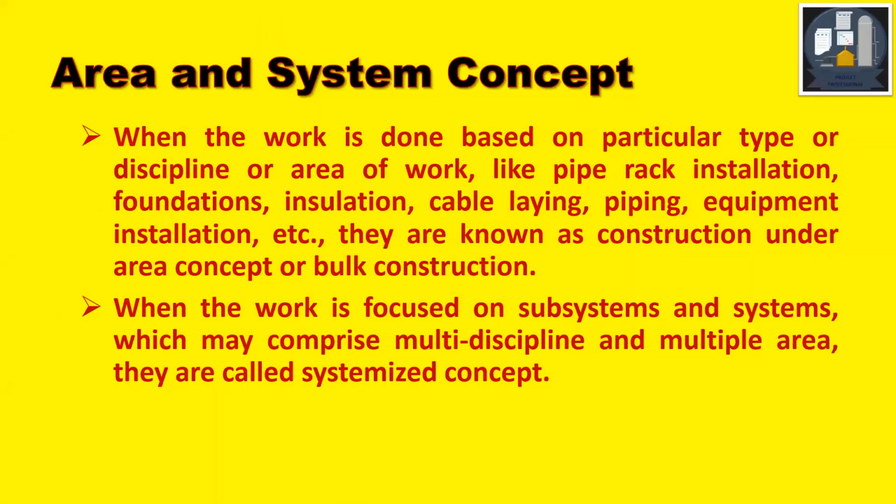To start with, let me explain what is systemized concept. In order to know that, you have to know what is area concept. When the work is done based on a particular type or discipline or area of work, like pipe rack installation, foundations installation, cable laying, piping, equipment installation, etc., they are known as construction under the area concept or bulk construction. While when the work is focused on subsystems and systems, which may comprise multidiscipline and multiple area, they are called systemized concept.